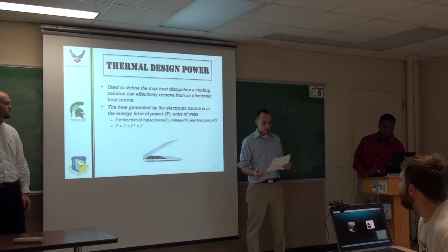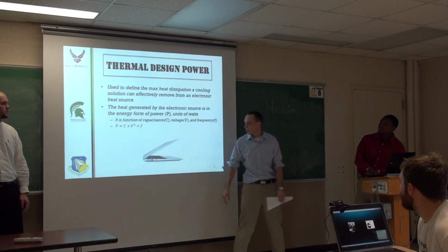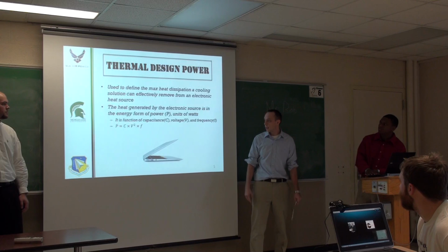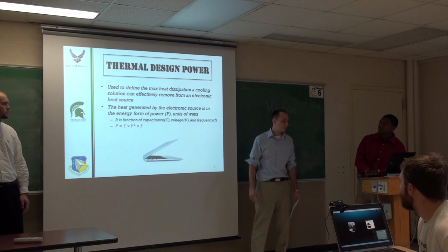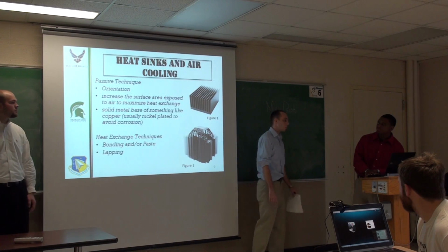The heat generated by an electronic source, remember, is in the energy form of power, which is given by units of watts. And right here is the equation that TDP is calculated by, which is capacitance, voltage squared, and frequency. Next, I'll be giving it to Cerrone here to cover heat sinks and air cooling.